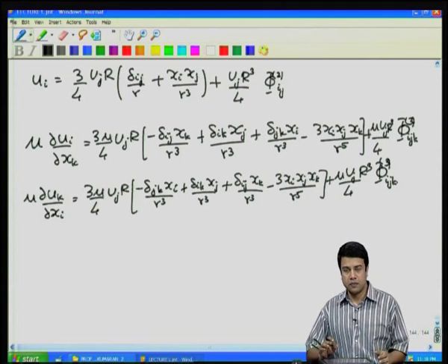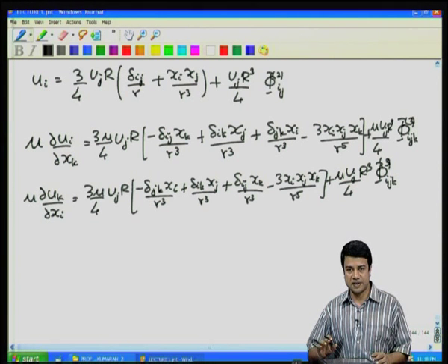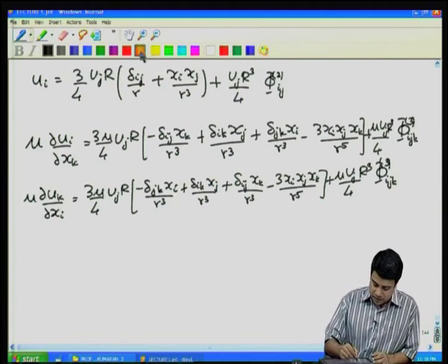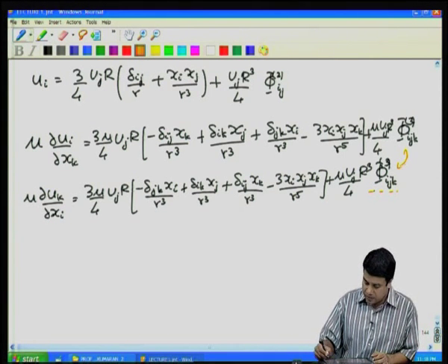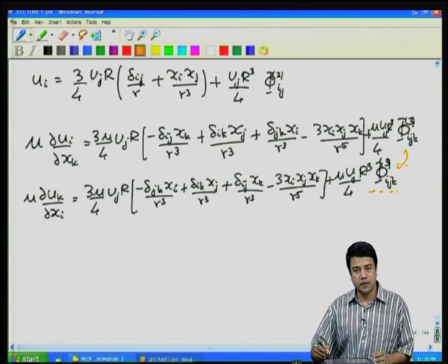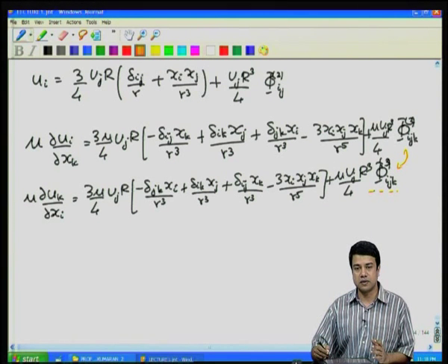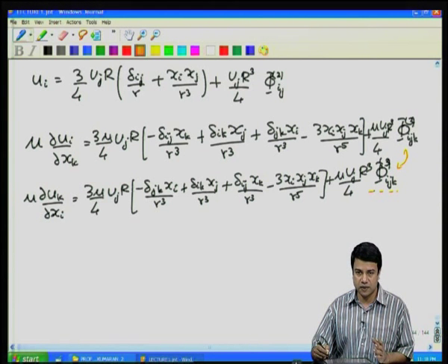When I take the gradient of phi j k with respect to i in this last term here, I get something that is identical to what I had got here, because both of these are obtained by taking 3 gradients of the fundamental solution. I take the fundamental solution, partial with respect to k gives me phi 1 k, partial with respect to j gives me phi 2 j k, and then with respect to i gives me phi 3 i j k. The way you take those derivatives does not matter. So, therefore, you get exactly the same result for this last term, which we will evaluate a little later.